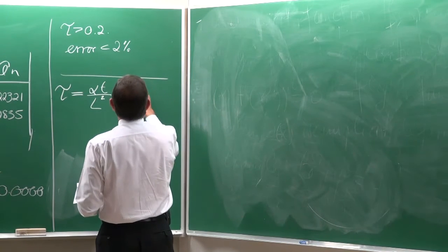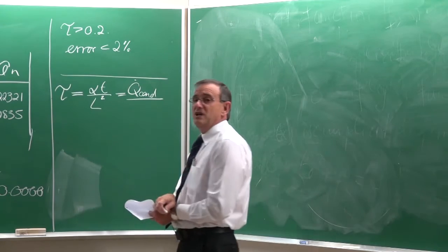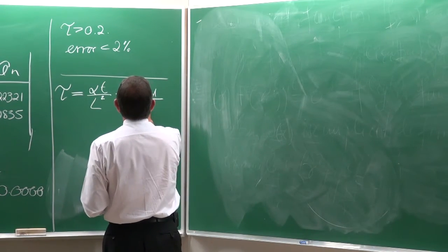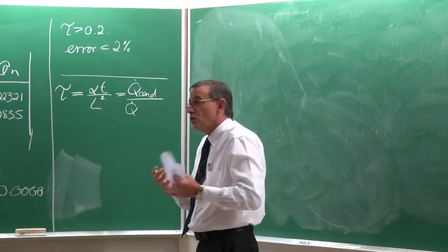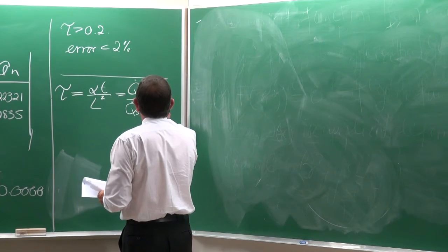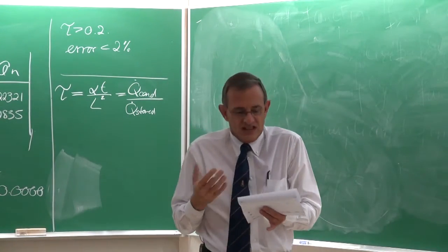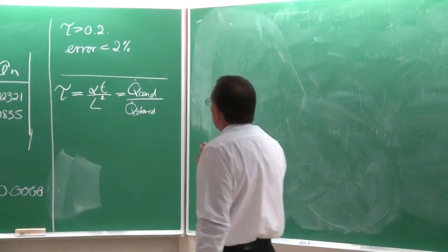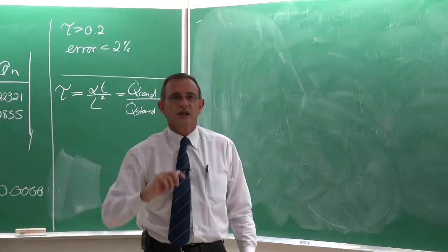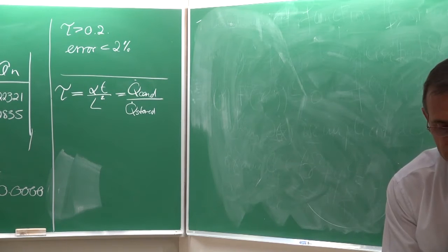And if we analyze it, and we don't have enough time for that, it is the ratio of the conduction heat transfer to the rate at which heat can be stored or released in the body. So how quickly the heat can come in and how quickly it can come out. So the Cp comes out, and that Cp is actually then that alpha. You remember? It is in that term there. Okay, so that is what the Fourier number means.